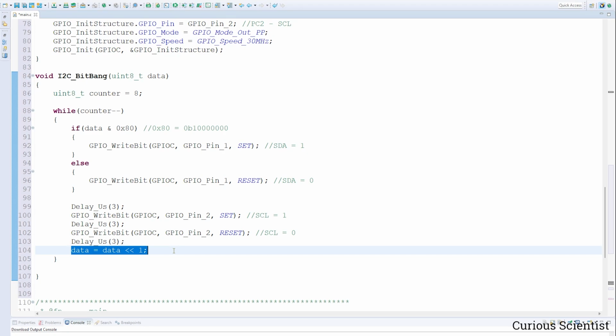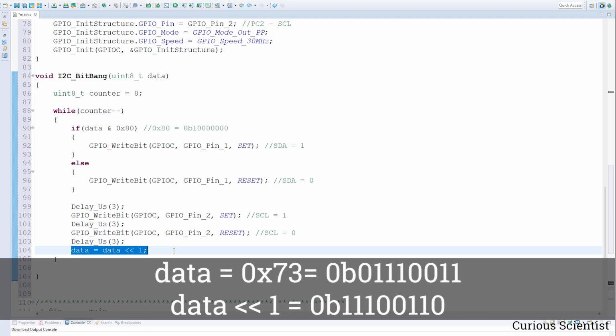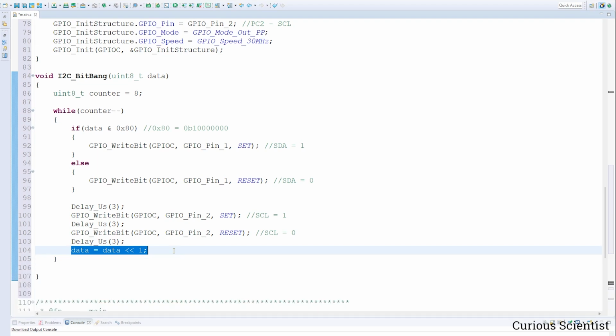previously second bit. And I just put an illustration on the display so you see how the bit shifting works, but I explained it in so many of my videos, especially in this series, that you could know this by now. But basically every time we shift the data back, so actually we can go through all the 8 bits of the data variable, and each time a new bit is masked out because of the shifting.